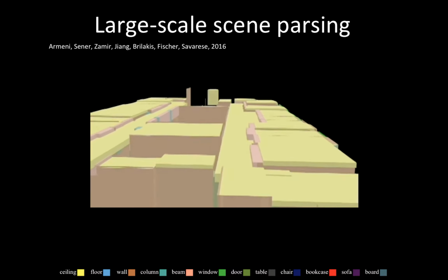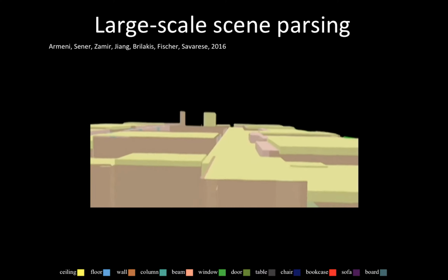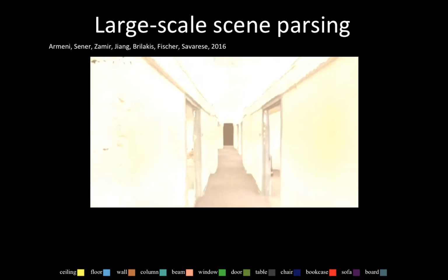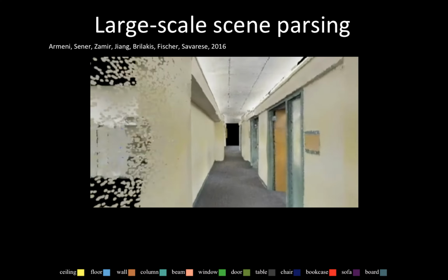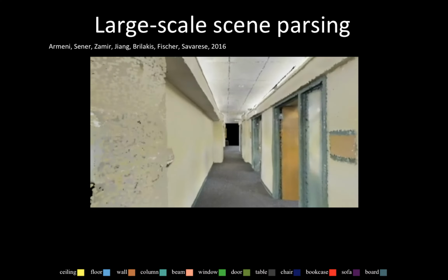So we have shown that it is possible to turn these large-scale structures into informative and functionally meaningful building elements called building information models, or BIM. Building elements include, for instance, corridors, rooms, hallways, as well as walls, tables, and windows. The key innovative aspect of this work is that BIM parsing is evaluated at unprecedented large scale, following a procedure that is fully automatic and hierarchical.